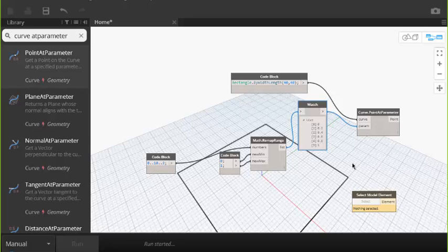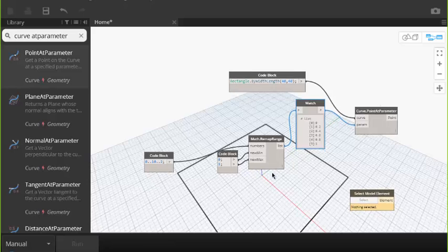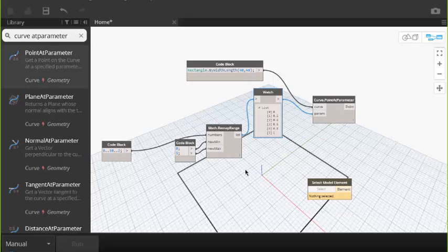And I believe the color range, when they introduce color in Revit, needs an input of values between 0 and 1. So if we want to, say, assign a distribution of colors based on areas, we can certainly extract that information from Revit, but then this list of areas has to be mapped into color values between 0 and 1 in order to let Dynamo pick a specific color. So yeah, that is remap range.